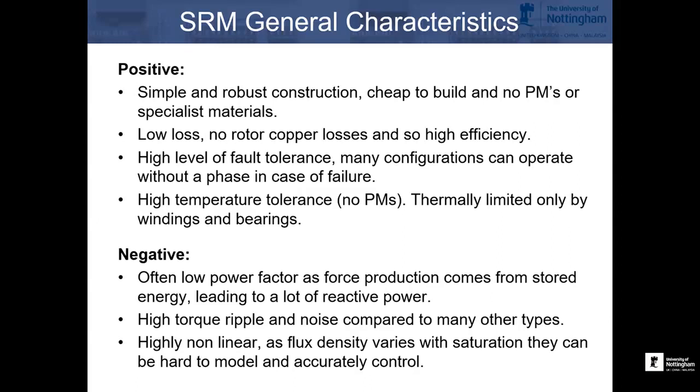But the chief issues with these are they have a low power factor. Because our force production is from stored energy, there's a fundamental limit to how much power you can get out of them, given that you're always balancing stored magnetic energy with output power. And they typically have high torque ripple and high noise due to that behaviour, as well as highly non-linear performance, which is quite hard to model and control.